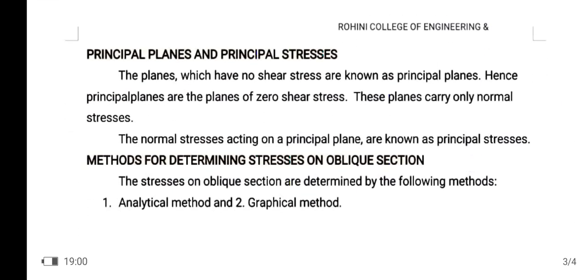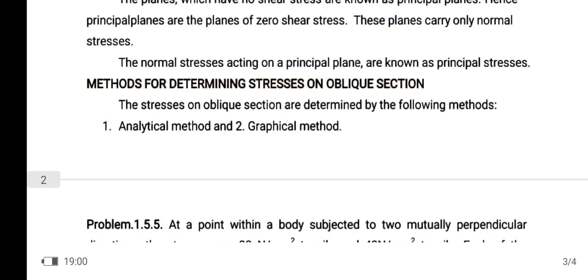Today's topic: principal plane and principal stresses. The planes which have no shear stress are known as principal planes. Hence, principal planes are the planes of zero shear stress. These planes carry only normal stresses. The normal stresses acting on a principal plane are known as principal stresses.